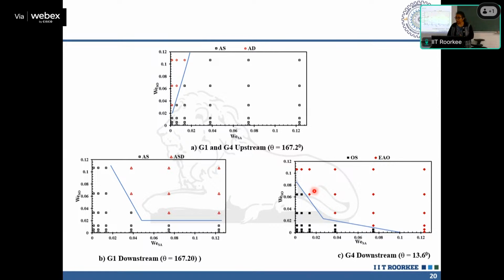Here we have organic phase slug and encapsulated aqueous slug. Okay, so this encapsulation is the new thing that we are seeing. So this is a water droplet encapsulated inside the toluene one. So this is a new flow regime, altogether new, that has not only appeared but also occupied a dominating part of the flow pattern map. Okay, so this is what happened when you combine things together.